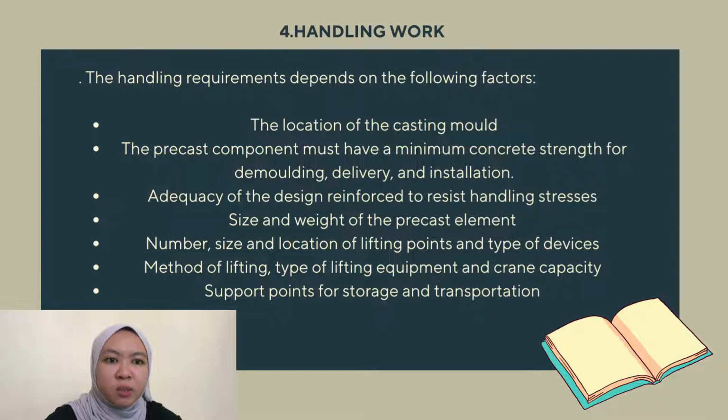The handling requirement depends on the following factors. The first one is the location of the casting mold. The precast component must have a minimum concrete strength for demolding, delivery and installation. Adequacy of the design reinforcement to resist handling stress. Size and weight of the precast element. Number, size and location of lifting points and type of device. Method of lifting, type of lifting equipment and crane capacity. Lastly is support points for storage and transportation.